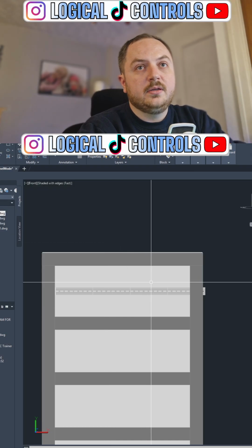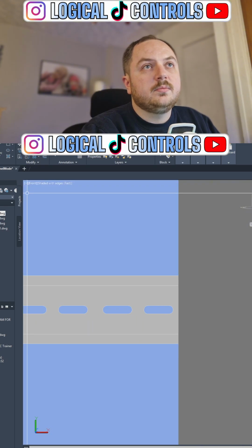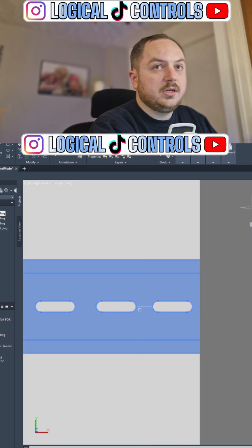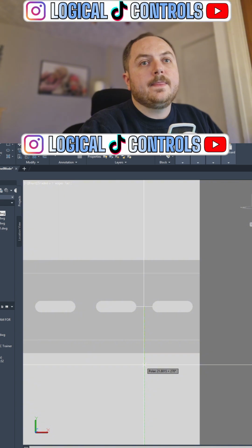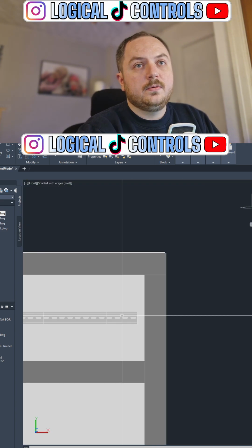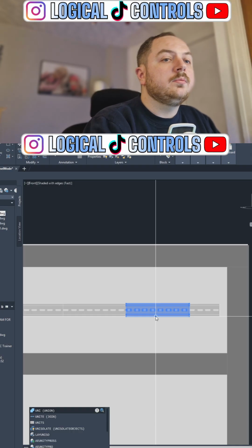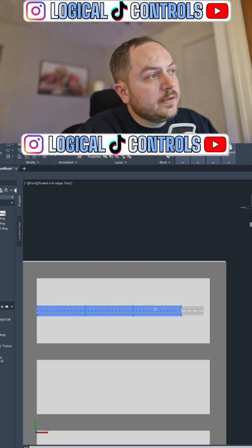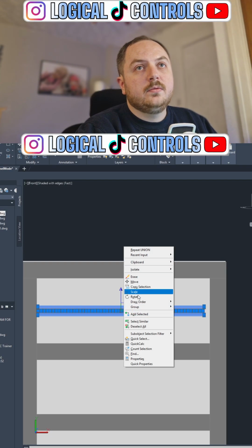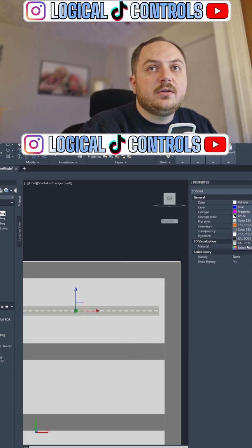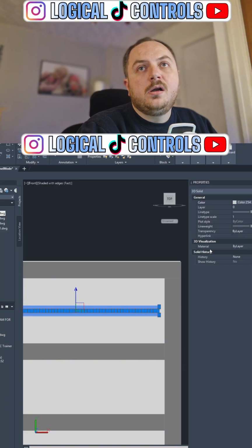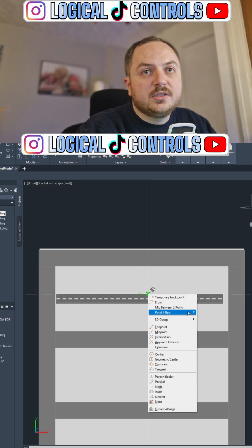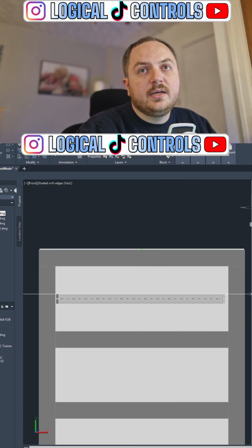Let's put that 10mm in. Find a good point to slice, and we're just going to slice it there in the middle. So put a line across there, do a slice on that. I want it vertical, there we go. And now I can do a union to join them all together, because at the minute they're all individual parts. I think you can see that okay, can't you? There we go. Check the colour again, because I think every time you do a slice it loses its colour. It's quite annoying. That colour there. Alright, there's our DIN rail. Let's put it perfectly in the centre. Line up X axis. There we go.